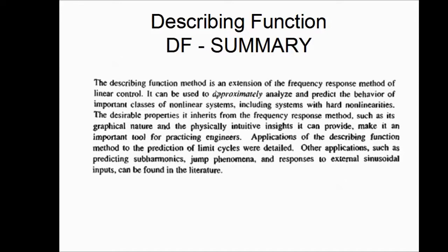So the describing function method is an extension of the frequency response method of linear control. It can be used to approximately analyze and predict the behavior of important classes of nonlinear systems, including systems with hard nonlinearities. The desirable properties it inherits from the frequency response method, such as its graphical nature and the physically intuitive insights it can provide, make it an important tool for